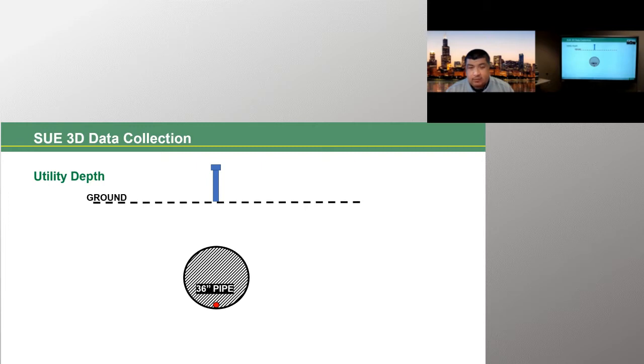The routers themselves are also made to be detectable, which allows another option or method to trace the line out. So for this demonstration, the depth estimated here is at 9 feet. So understanding these different types of technologies and how electronic depths are derived from each is critical for the SU field data collection process, which is what I'm going to cover.